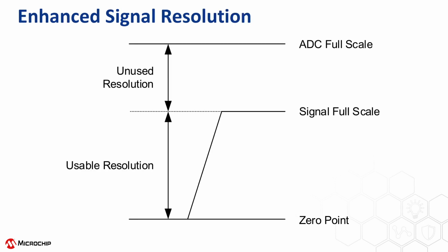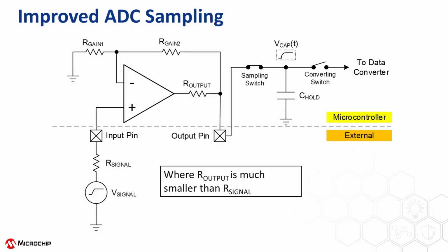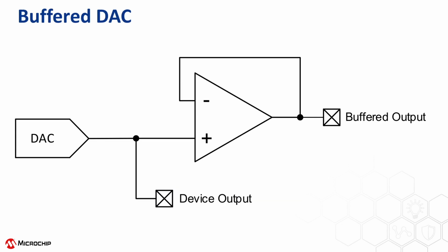Another common issue is where the input signal is not sized to the input range of the ADC. When improperly sized, the resolution of the signal is not optimal since some binary codes will never be reached. The integrated op-amp provides a space-efficient method of buffering and scaling the input signal, which can improve signal acquisition time and resolution.